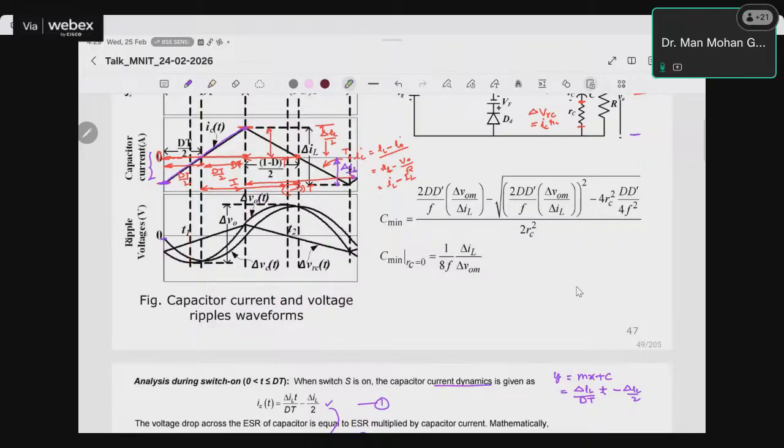But if I have this expression with me, then if I differentiate it with respect to T, this will give me the value of T1 at which this voltage is minimum, right? Similarly, this side, if I differentiate this expression, we will see how this expression is obtained. I'll get the maximum value of del V naught at T2. Now, if I take a difference of these two values, then this will give me output voltage ripple. That is the task we are going to do, right?